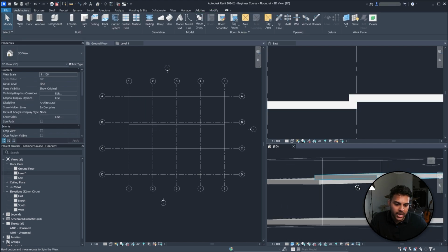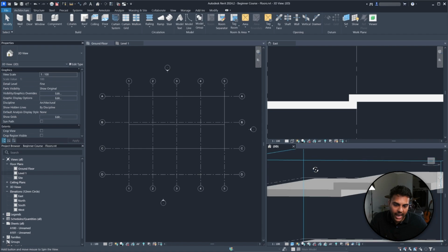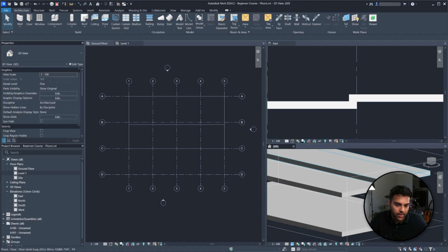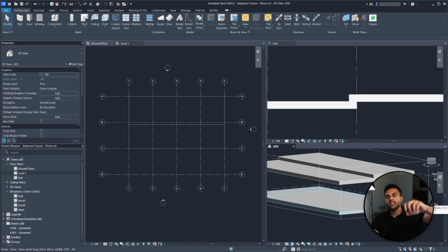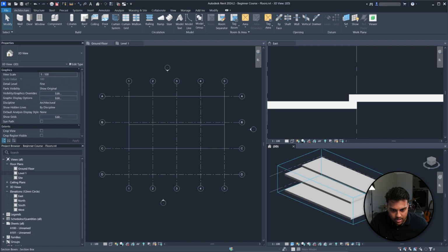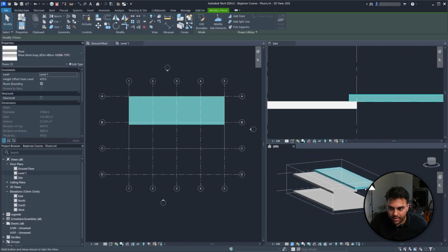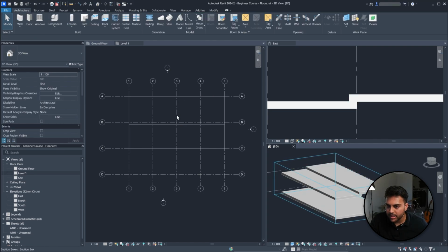But the geometry has allowed you to join it, and it looks as if on the Revit model they've been joined together. So when you want to export this and send it to another subcontractor, when they link it into their Revit file as an engineer, they'll say, okay, the slab is stepping up and it's joined, right? So that's how you would go about trying to shift things around, join things, and everything like that.